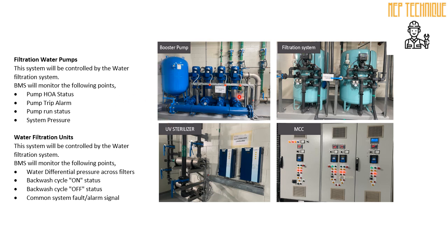But in a parallel building, not a very high building, but parallel buildings such as school facilities or malls, there is a booster pump directly. You will not find a transfer pump in that case. Then the booster pump, in most cases, will be monitored by BMS, such as pump hand, auto, off status, pump trip alarm, run status, system pressure.